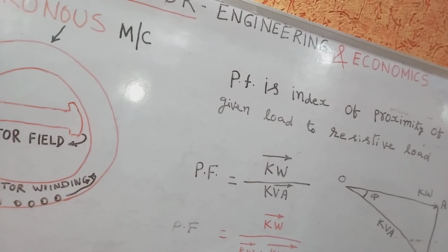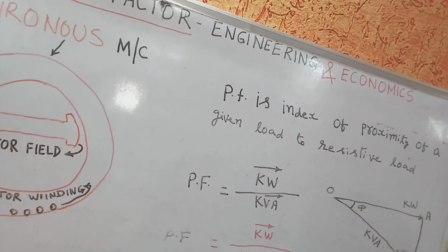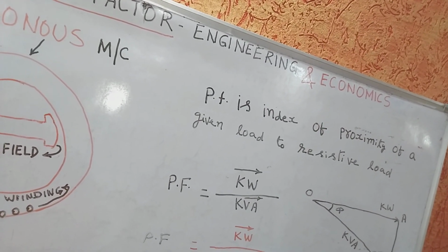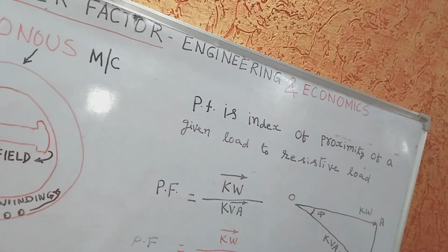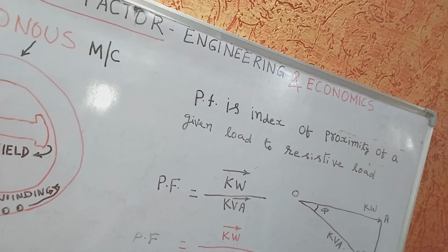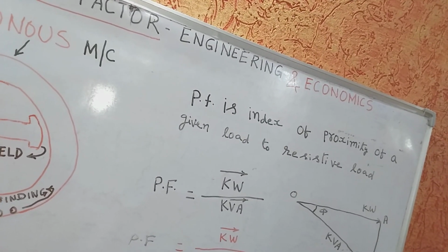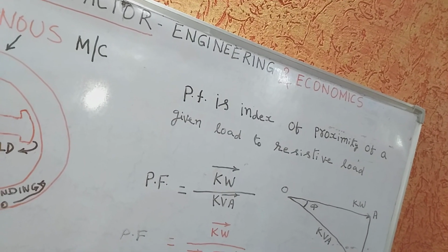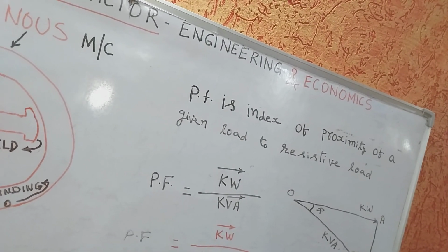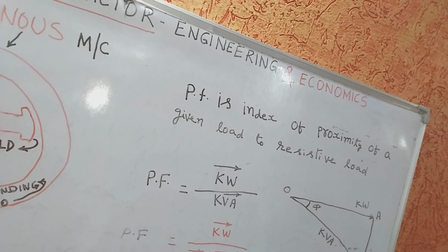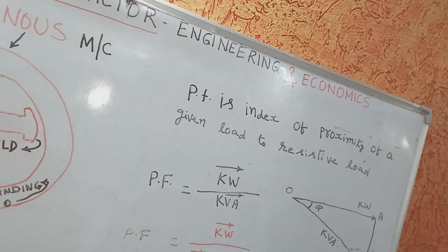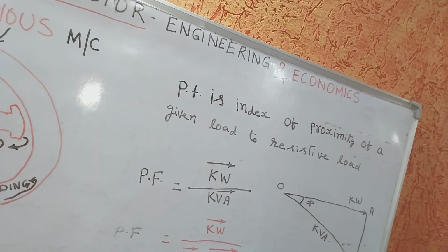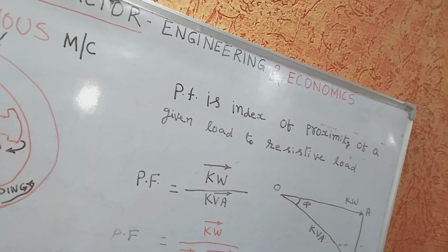Both synchronous and induction machines may become self-excited when a sufficiently heavy capacitive load is present in their stator circuit. The capacitive current then furnishes the excitation and may cause serious overvoltage or excessive transient torque. Because of the inherent capacitance of transmission lines, the problem may arise when synchronous generators are generating long, unloaded, or lightly loaded lines.